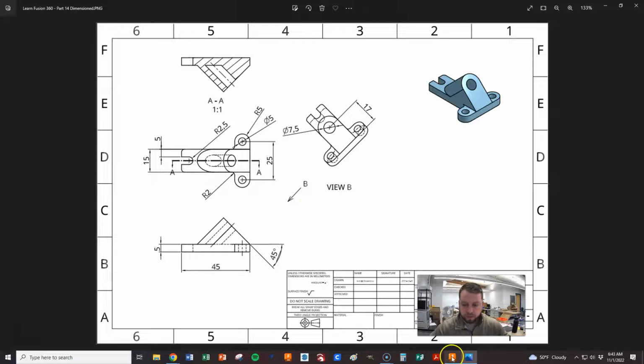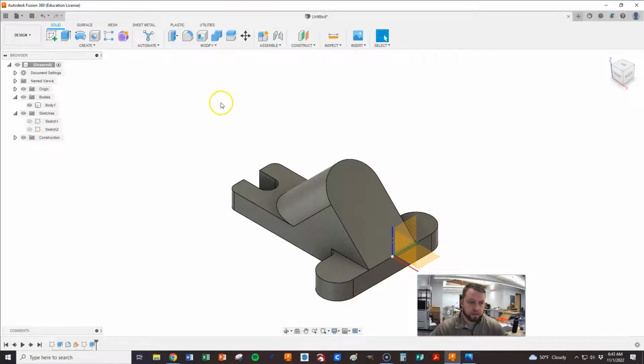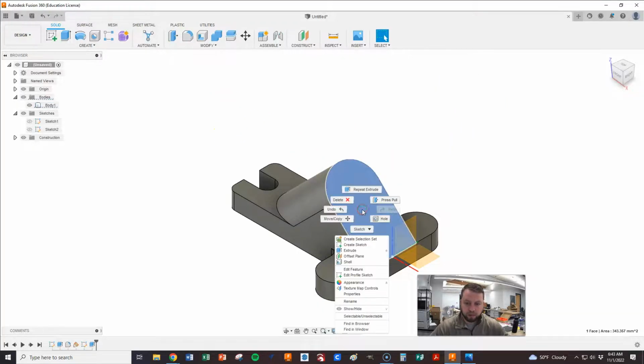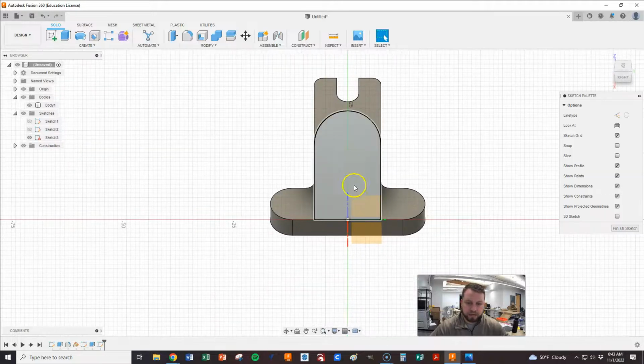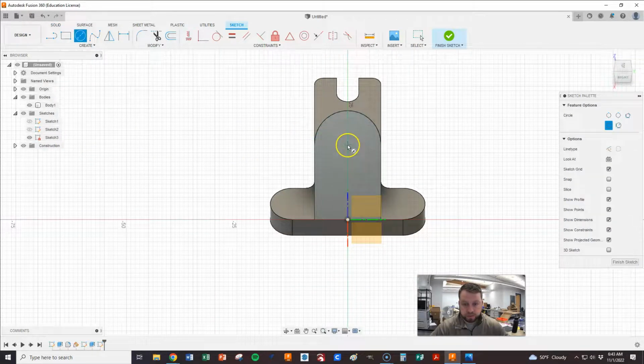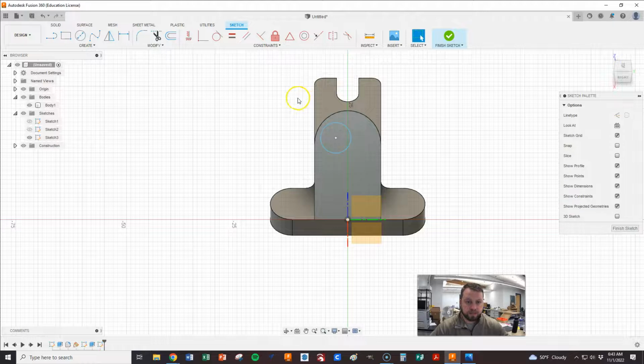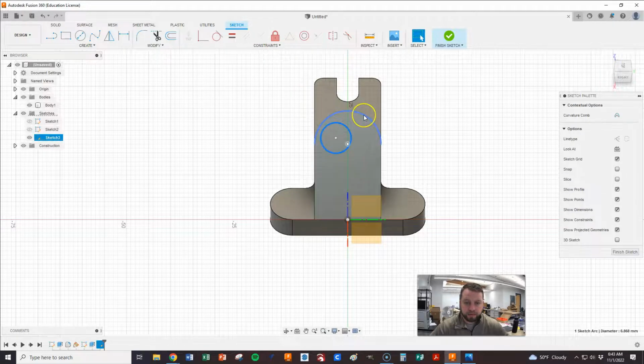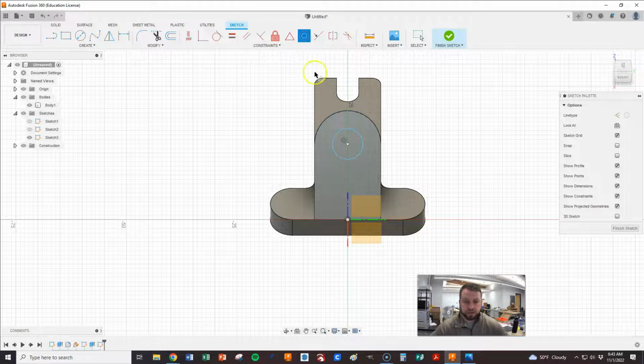If we went back to our drawing, let's create a new sketch. So I'm hovering here, right-clicking, and creating a sketch on that surface. I can create a circle, and just by hovering, that little dot tells me that that's the center of this. But if I wanted to use constraints, let's just do it this way. Hit escape, and then I'm going to hit this, and hold shift and hit this, and say, yeah, I want you guys to be concentric. We'll snap it back in that way.